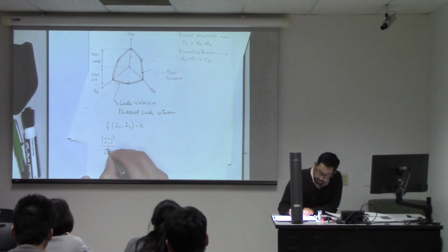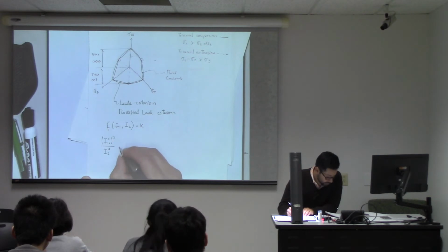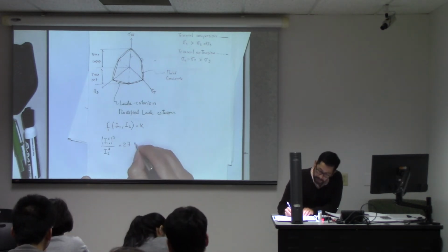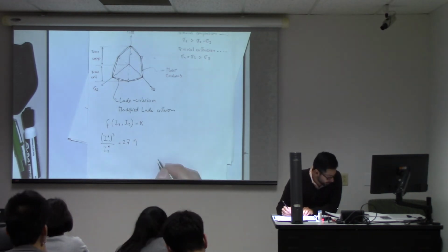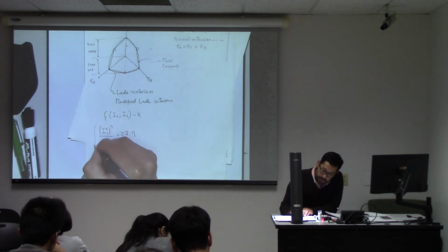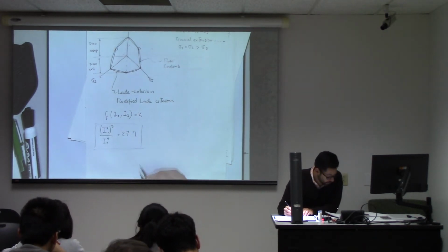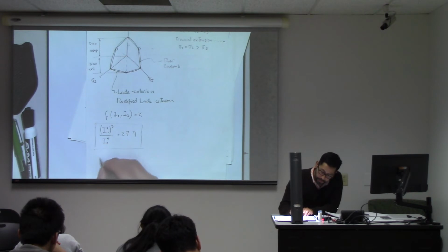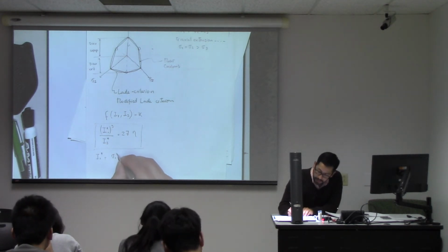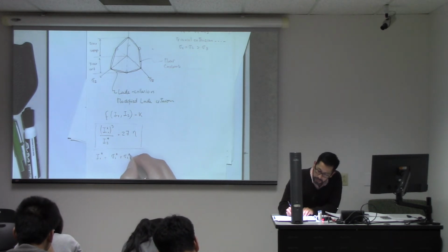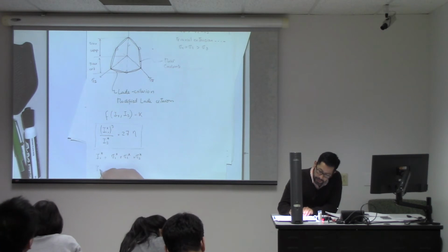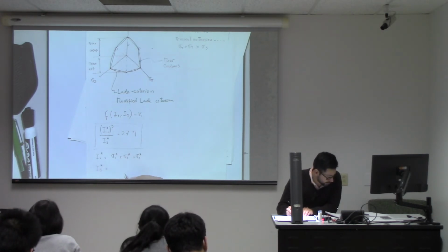So these are just invariants. The star, I'm going to explain that in a bit. The star is a correction. And so this is the main equation. We know what invariants are, but I'm going to write it here anyway. This is in terms of effective stress. Always, all these failure criteria are written in terms of effective stresses.